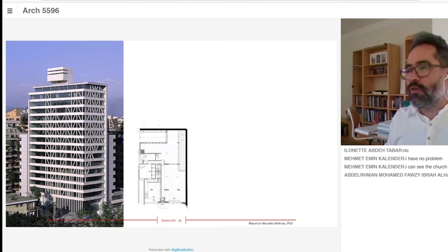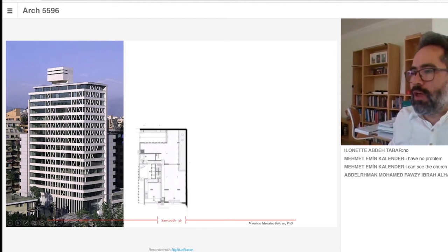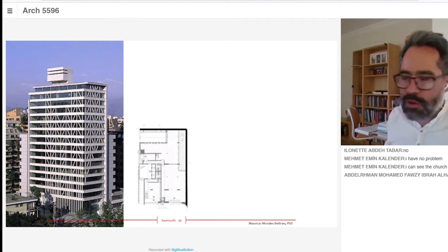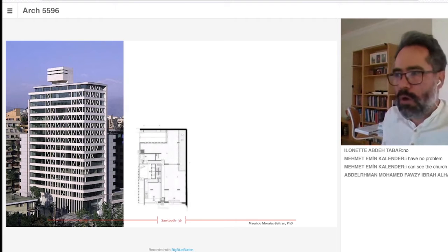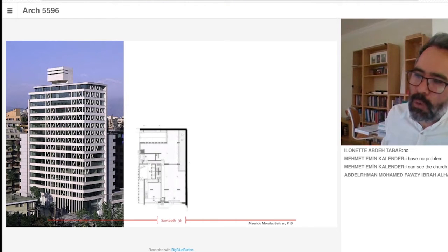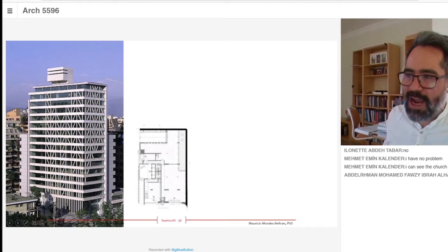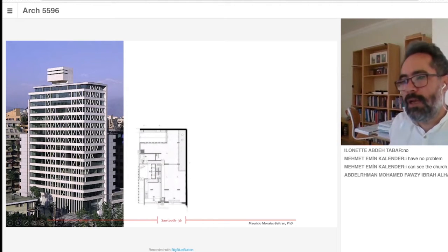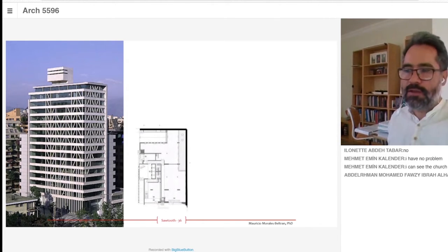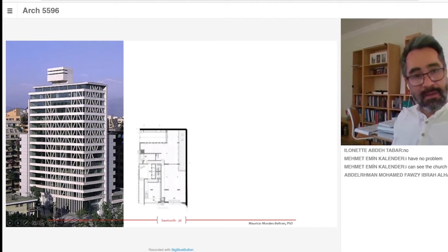Of course, if we do that, then we are going to have huge walls on the facade, and the architects didn't want that. So how can we solve this? The architects worked together with the engineers and came up with this solution, which is some sort of brace, namely diagonal, in the facade, in such a way that the stiffness of these two facades can be very close to this one by using a different element. And at the same time, there is some degree of transparency, so the offices behind are not really closed.